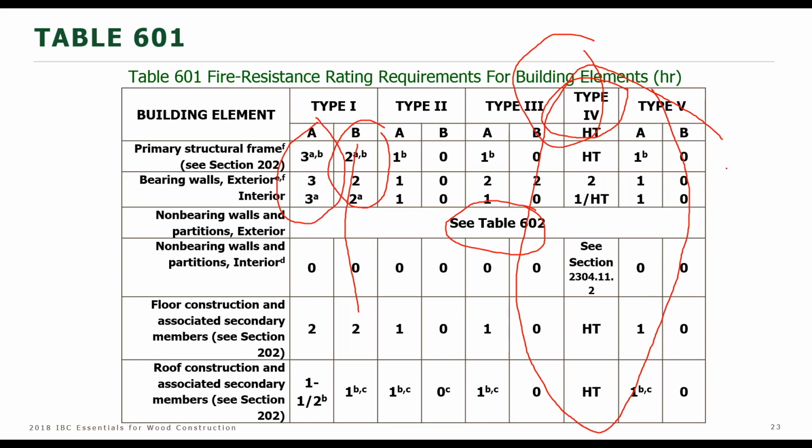So it's like a current heavy timber building. Current heavy timber buildings do not require any protection on the elements, any gypsum protection. They perform very well. They're limited to 85 feet above grade for most occupancy groups without protection, and that'll be the same for Type 4C. But the difference with Type 4C is that it will require a rating of 2 hours throughout, even though it can all be exposed. So, excellent.